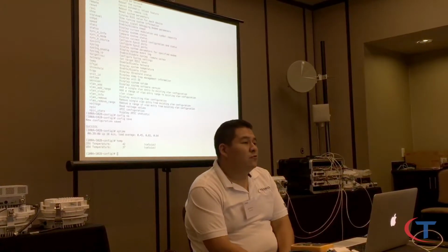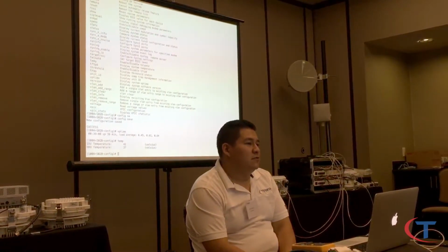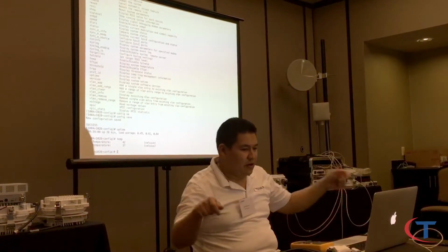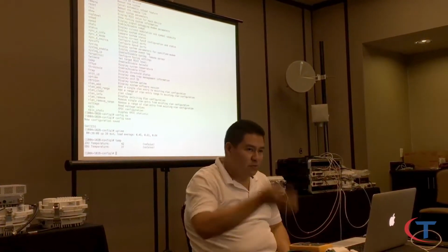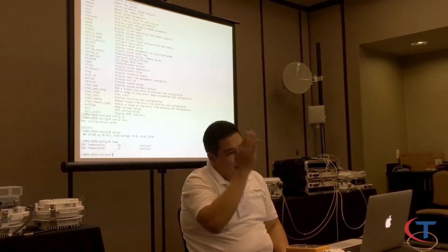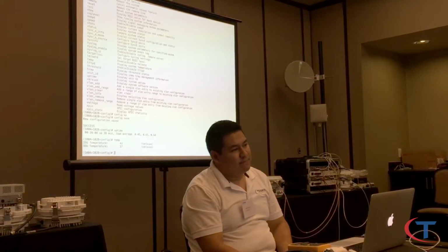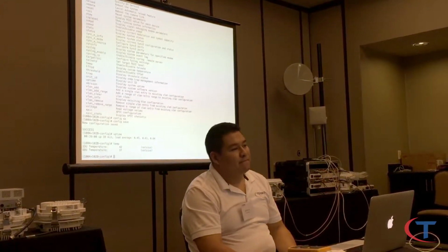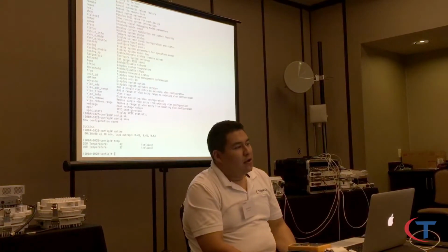Yeah, you gotta sweep the cable and look at the frequencies come in return from the cable loss. So there's a special analyzer you put and then connect it. And there's a transfer frequency, receive frequency, and telemetry as well. It's really you just need an antenna analyzer, and just treat the LMR as an antenna, and then just see how it behaves. Yeah. So a load on the end of it, maybe.